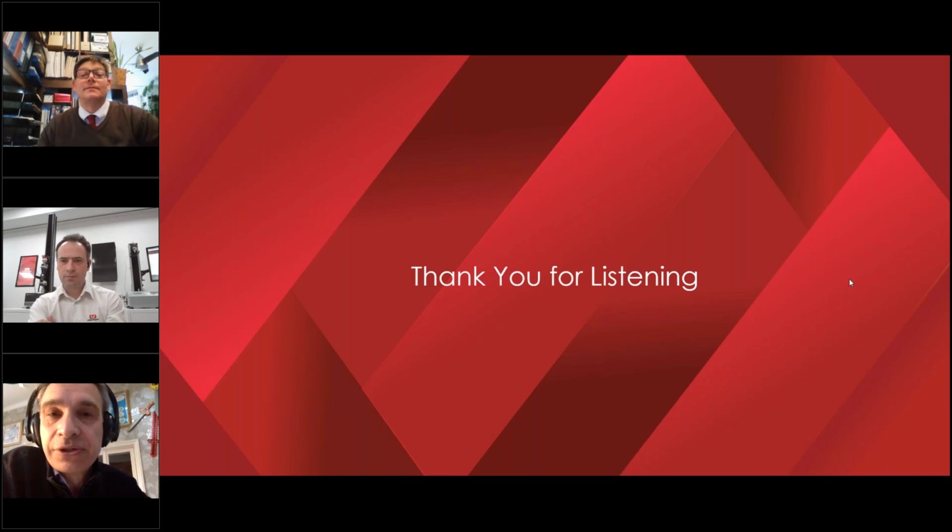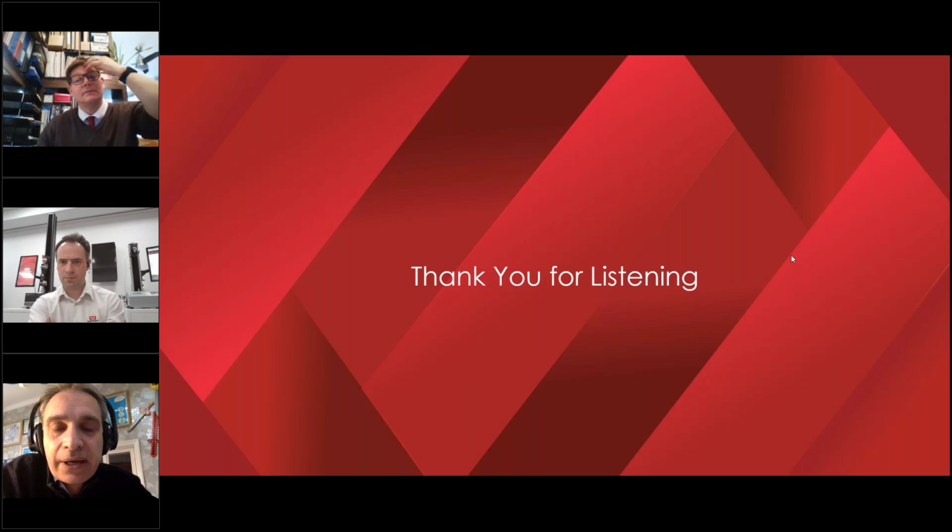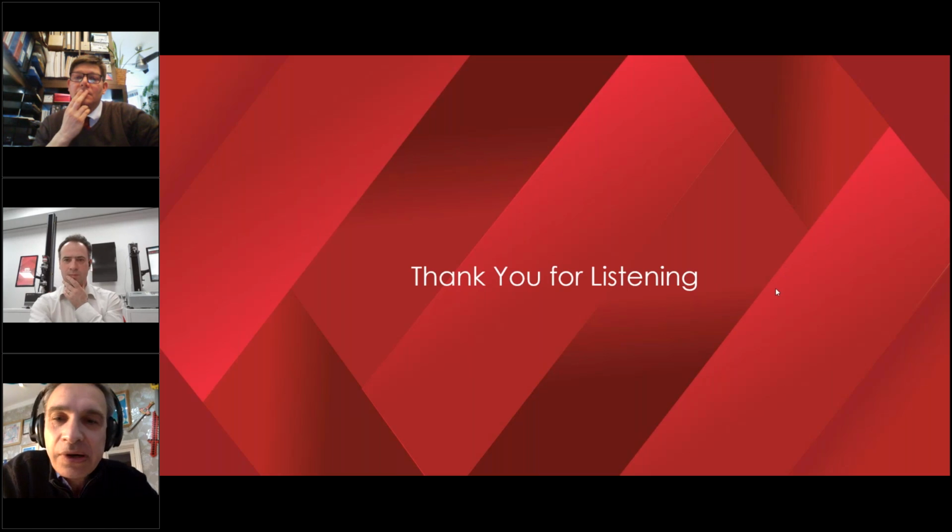Yeah, there's a form of DCPD called close coupled DCPD, where you bring the current connections in very, very close, within the limitations of the size of those connections, so you can maximize your resolution. But as Matthew says, there's a trade-off. You improve your sensitivity to cracking, and you improve your sensitivity to inaccuracies in the position of your connections. So it can be a zero-sum game unless you're very careful.